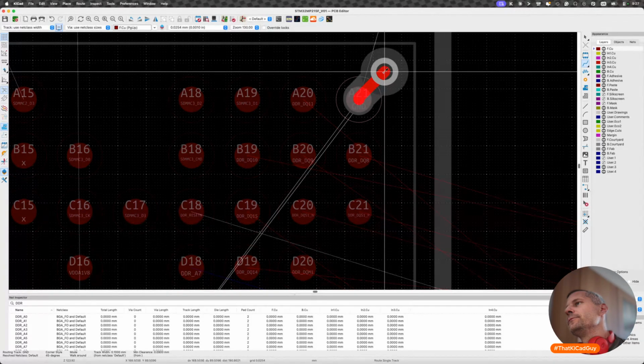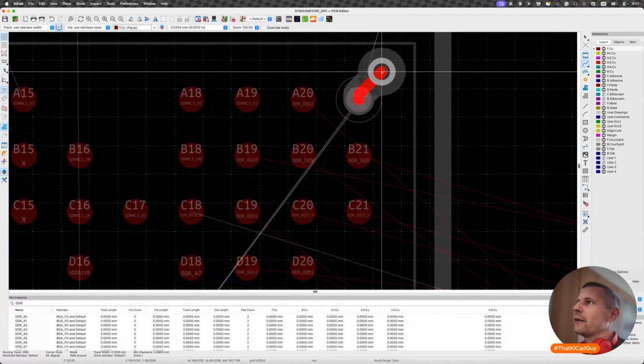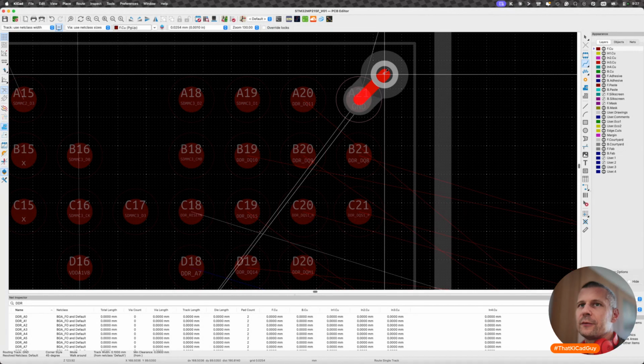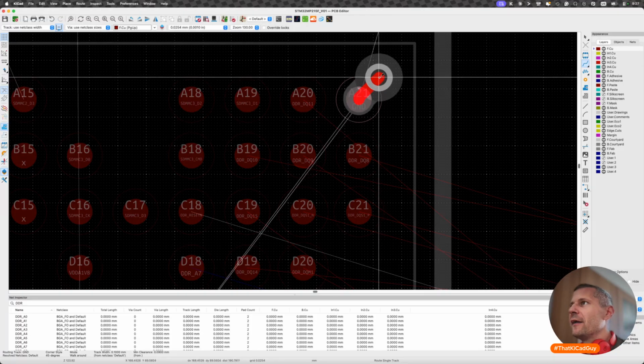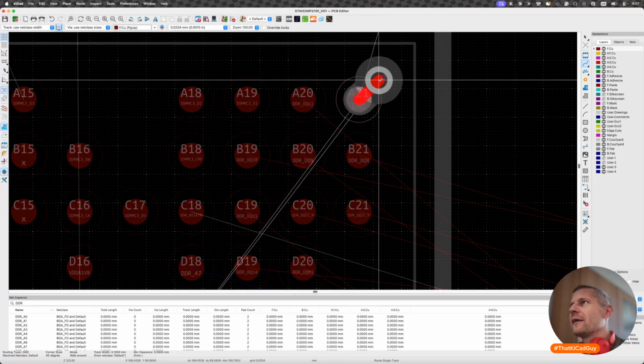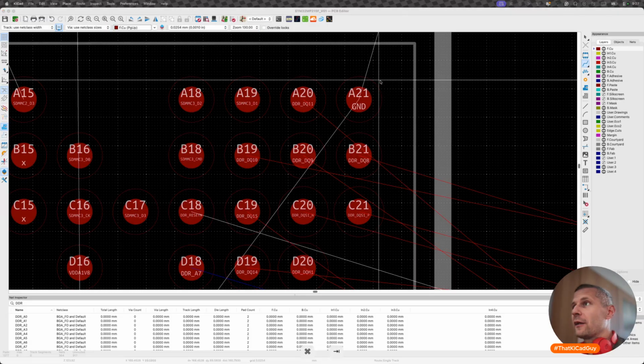Ideally, to avoid the solder wick effect, I want to place the via as far as possible from the pad, including the clearance. But this can be a challenging thing, and I think we can check the technology either way.